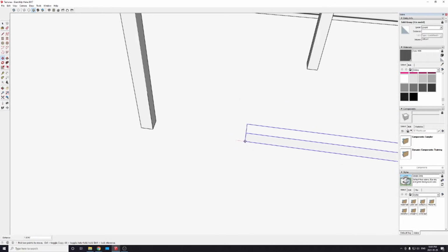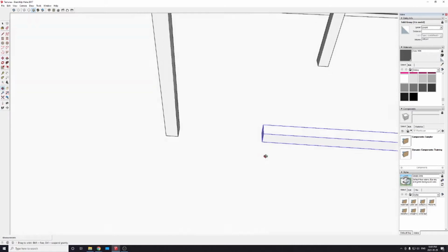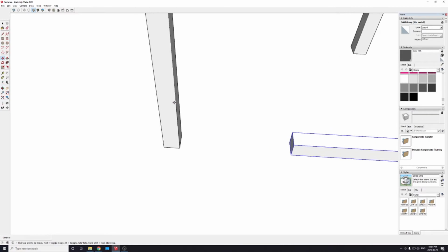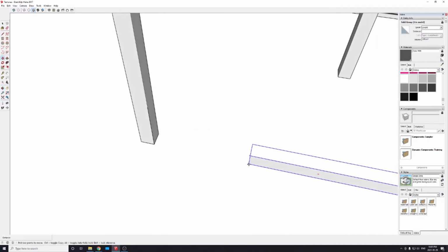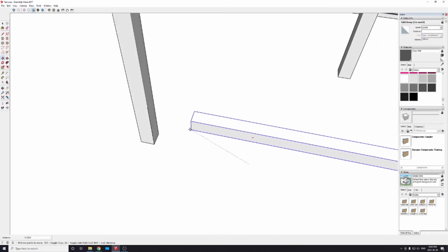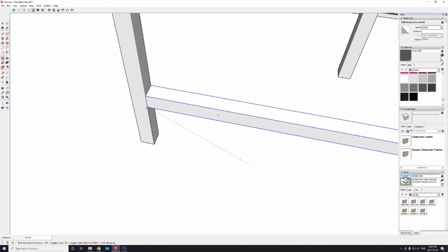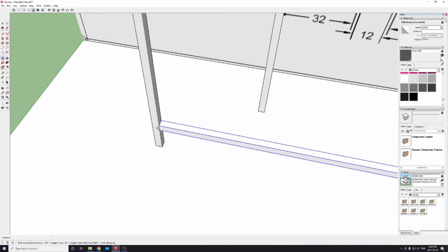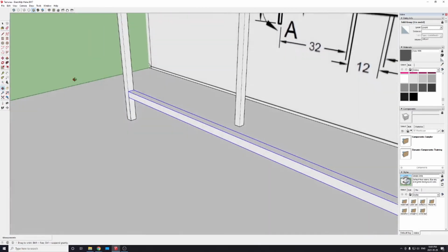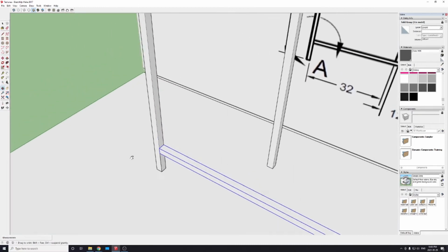But you can actually, if I hit escape there, if you pick a specific point, so I'm going to pick this bottom left corner of our piece of wood here, and you can see, doesn't matter how much I zoom in, there's my 8-inch line there. So I'm going to take this point and bring it right over until it snaps onto that green dot there, and then I know that it is sitting at 8 inches. Okay, and it's also properly aligned in all of the axes, so we're good in that respect.